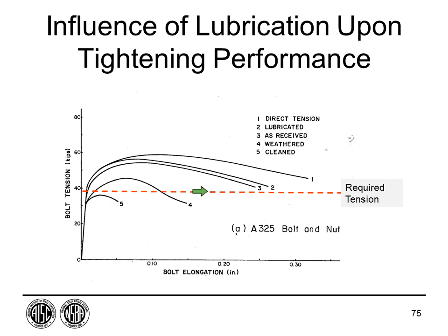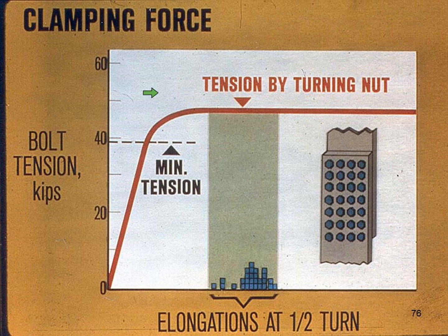This is a required tension of 39 kips, and it never made it. And it would fail actually probably during installation. So that's why we have in the bolt specifications this rotational capacity test. What we want is fasteners that look like this, where they have a nice level plateau. If this is the rotation we're getting from turn of the nut, then it doesn't really make much difference.